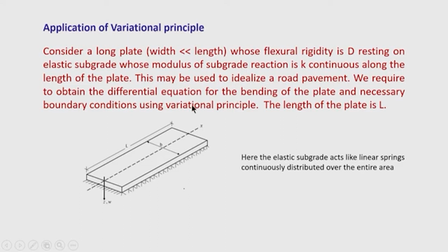So, this condition may be used to idealize a road pavement, because road pavement is usually rested on the subgrade, and you know that pavement is having a concrete slab in many cases. So, concrete slab acts like a plate, a very long plate resting on the elastic subgrade.